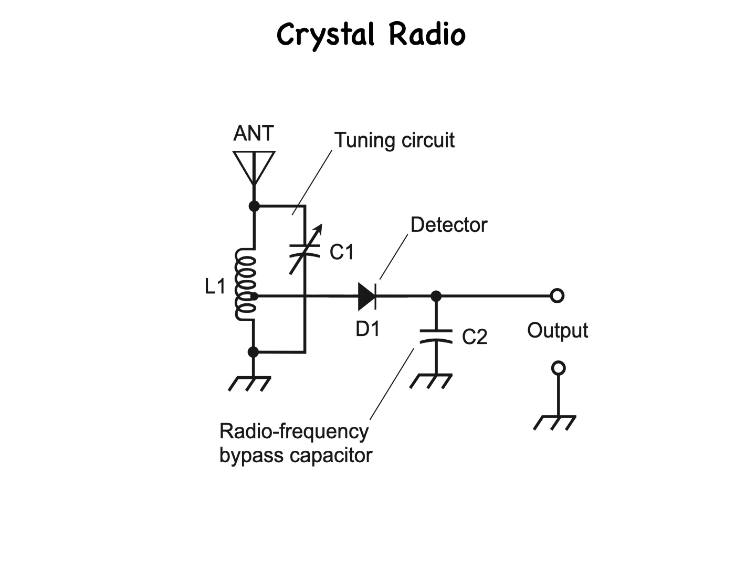In the crystal radio, RF energy from the antenna resonates, reverberates, in L1 and C1. The resonant frequency depends on the size of the coil and also on the setting of C1. That frequency determines which station you hear, if any. Diode D1 converts the signal to pulsating DC that contains both the RF and the audio from the original transmitter. Capacitor C2 shorts the RF part of the signal to ground, leaving only audio frequency, AF, energy at the output. The position of the coil tap must be adjusted experimentally for maximum output.